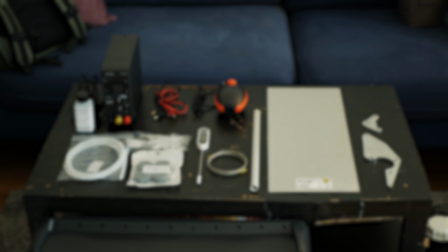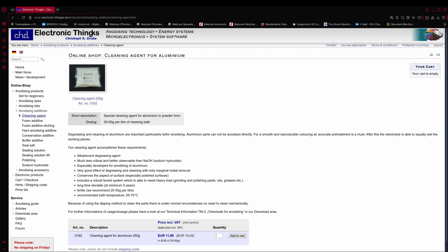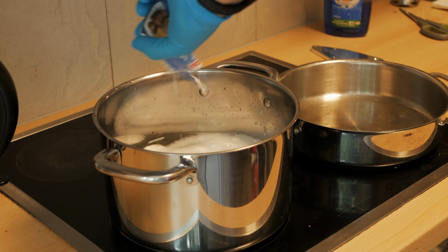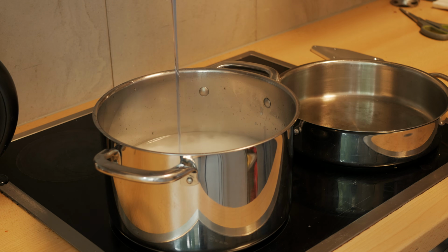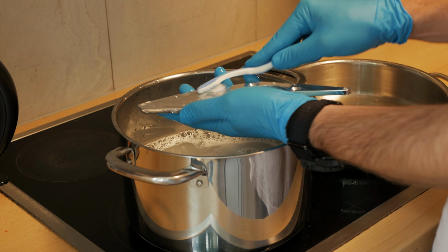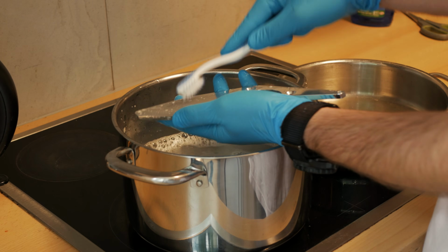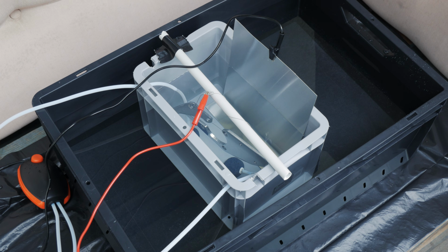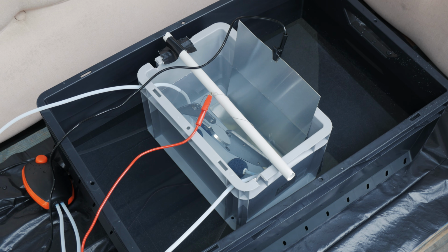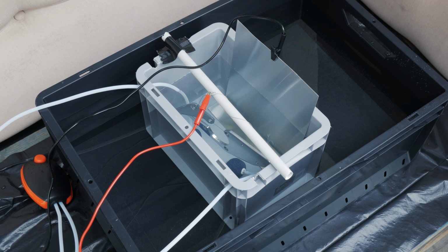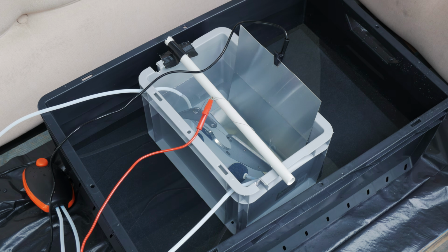I'll tell you what though, I sure did forget to order the surface cleaner to remove any residue from the polishing compound. However, my time in chemistry lab made me a firm believer in the power of baking soda and dish soap in a warm water bath. After some scrubbing, I cleaned the parts with isopropanol and hung them into the acid bath. Normally, you would use a separate activator bath with phosphoric acid or something, but as a hobbyist, hanging the parts in the sulfuric acid bath for a few minutes should do fine.